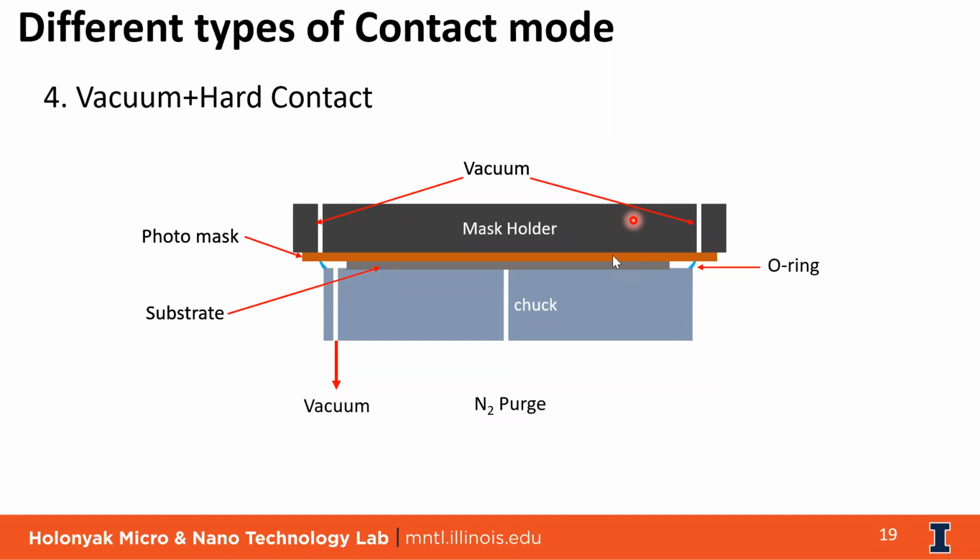Okay. So HMDS is generally used to improve the adhesion between the photoresist and the substrate. So what will happen is, if you have any trouble in your cleaning or you're leaving any contamination or the substrate is too much hydrophilic. So basically the substrate is hydrophilic in the sense you have some water vapors sitting on your wafer surface, right?